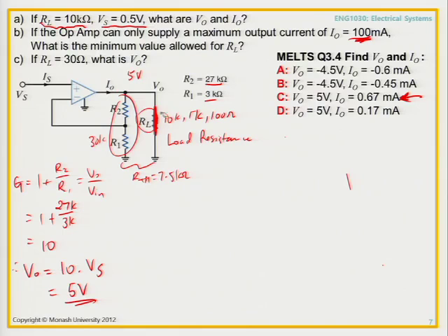So the question becomes, how do I calculate the exact value of RL that gives me, what is it, 100 milliamps? Algebra. Yay! Okay, good. So RL, you can calculate a couple of ways. So this is RL. You could say, well, you've got 0.17 milliamps down here for a 5 volt source. So you've got 100 minus 0.17 milliamps. So let's just call it 100 milliamps coming down here just to be approximate.